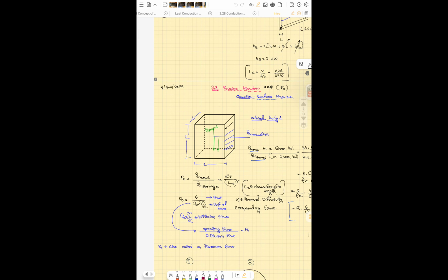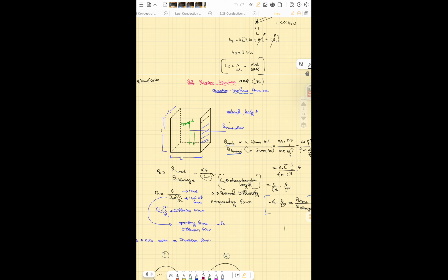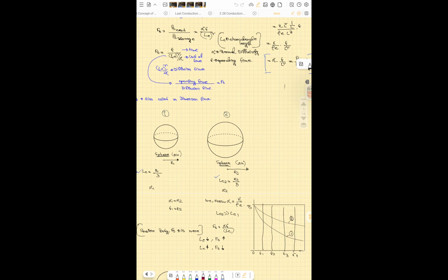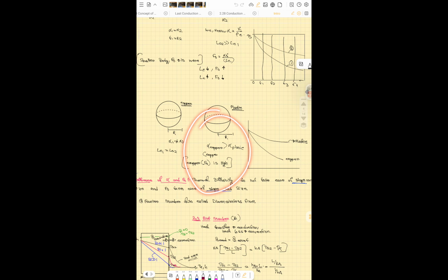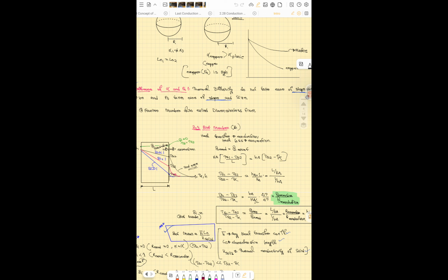Okay, I am now going to Fourier number. First, how will the Fourier number be? Fourier means conduction by storage, that is alpha t by L square, that is the Fourier number we are getting. Operating time by diffusion time. Then how is it related, just see, just remember one. Biot number is conduction by convection, sorry, Biot number, how do you remember?